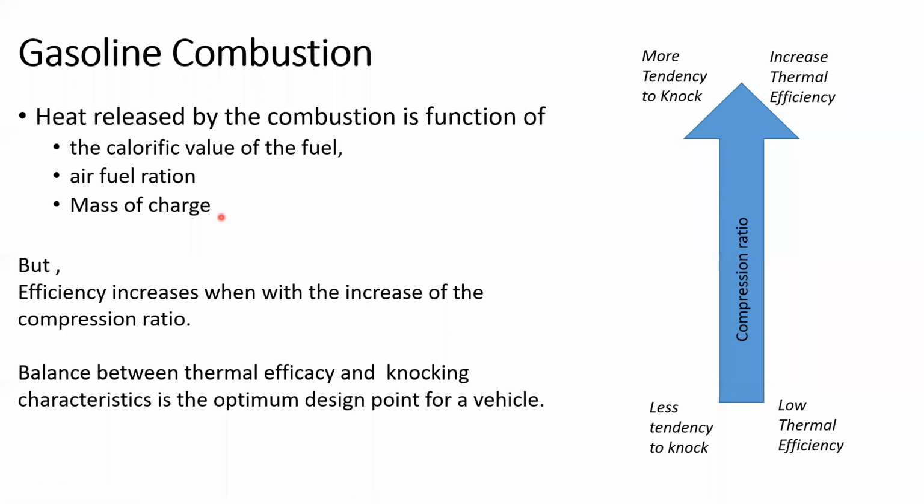That's why we have something called forced air induction. In forced air induction, we use turbochargers and superchargers to cram more air into the cylinder. More air into the cylinder means more pressure inside the cylinder, and more fuel has to be added, so we can actually get more power.